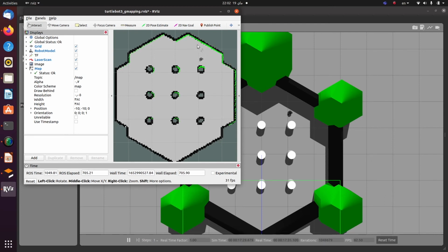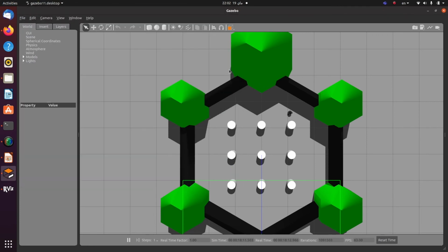But once you have a map like this, you can always make sure that there is some localization node running somewhere, because I cannot construct a map even if I'm executing individual mapping, unless I have the location of the robot somewhere from a GPS sensor or something. So rest assured, there is some localization node running, right? Whether you're doing SLAM, which is simultaneous localization and mapping, or doing some individual mapping and you have the localization data coming directly from a sensor. Alright, but since we're using gmapping, which is a SLAM algorithm, we know that we're both localizing and mapping at the same time.